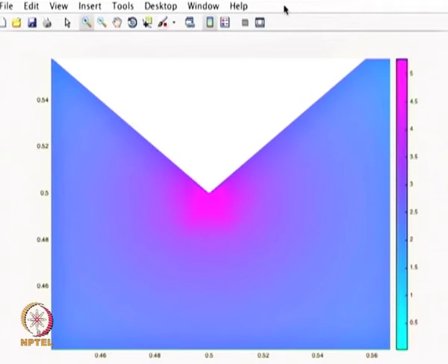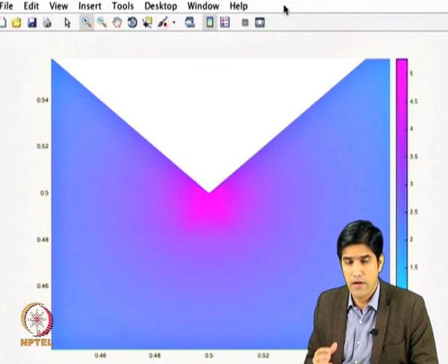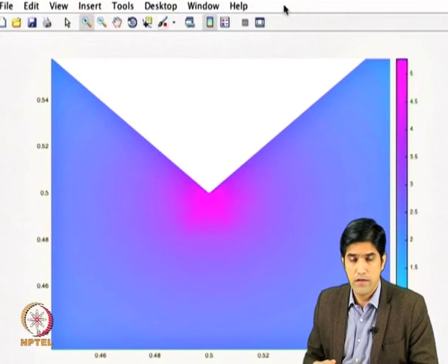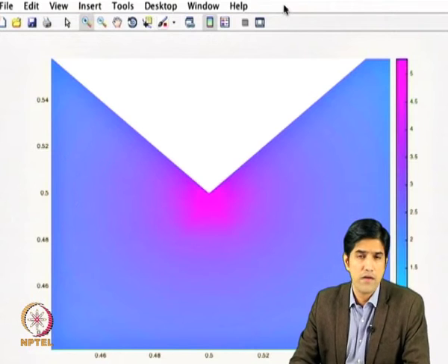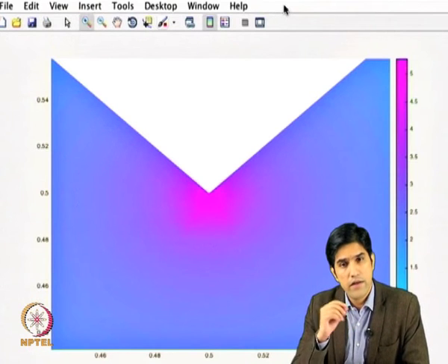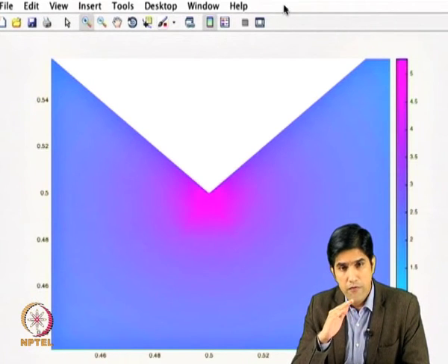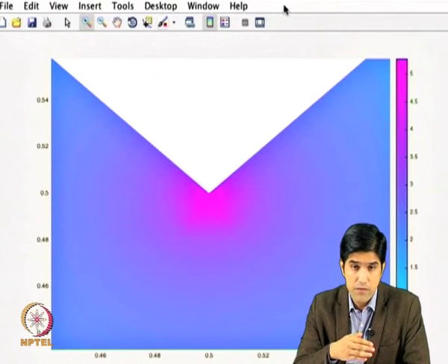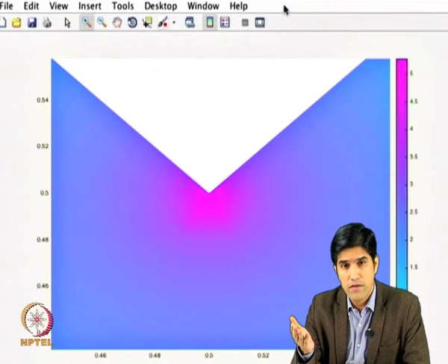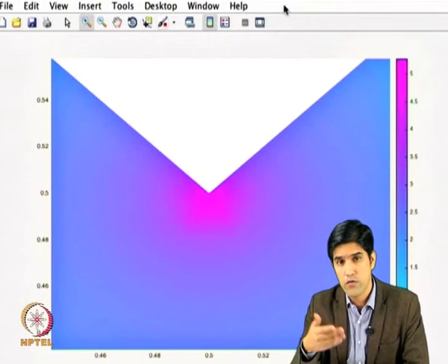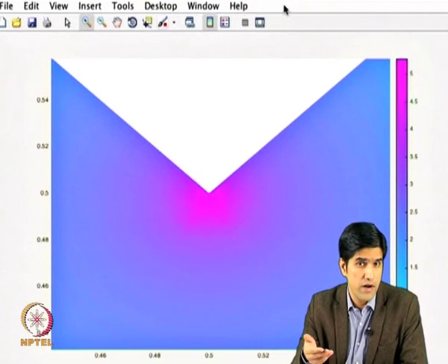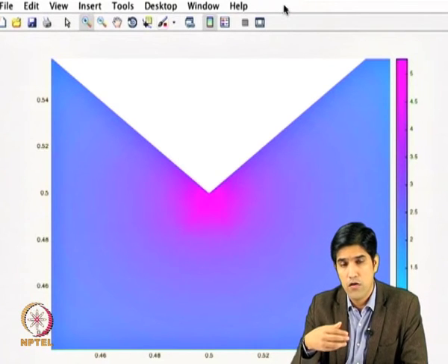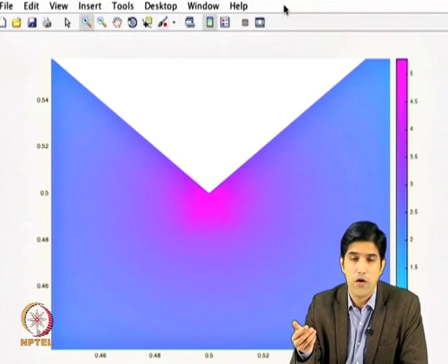So what we wanted to show here is, in some of the problems you gain something by refining, whereas in some of the problems the gain is not there. There is going to be a lot of other things happening. This is also something we saw in the case of finite difference method. By refining the grid, the error is going to increase because of various other reasons. For example, the number of points that we are going to use in the computer is going to increase dramatically, and because of that the truncation error or the numerical accuracy is going to change accordingly.